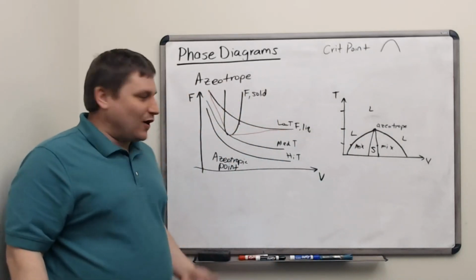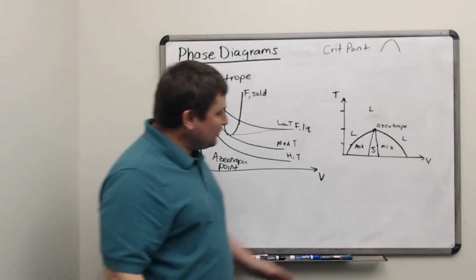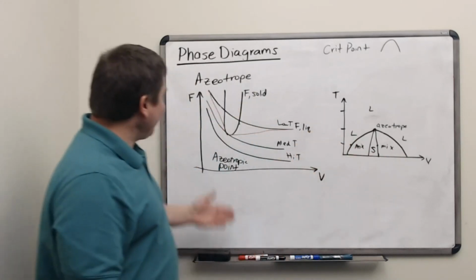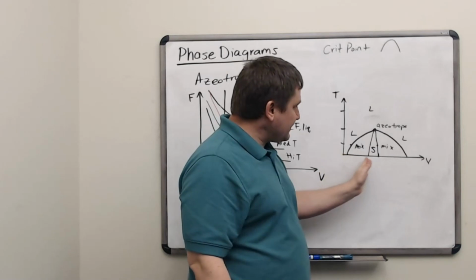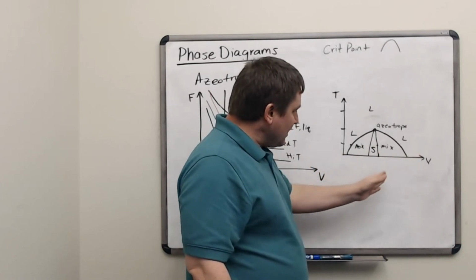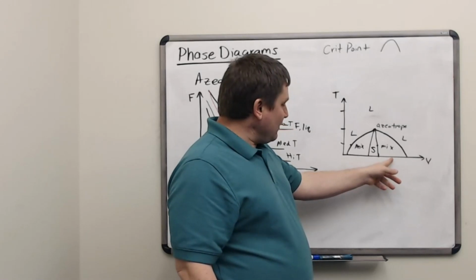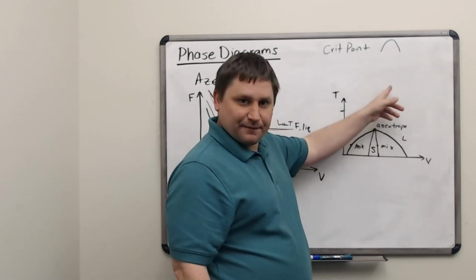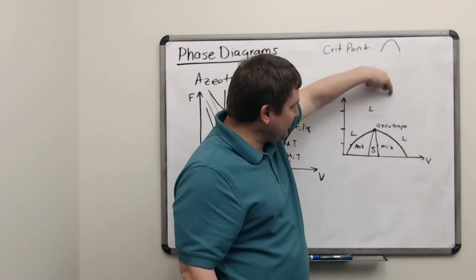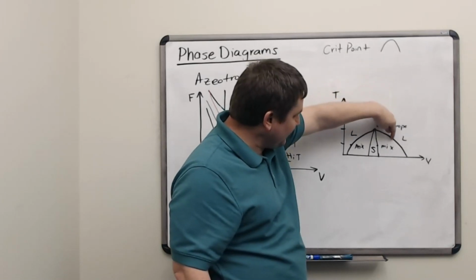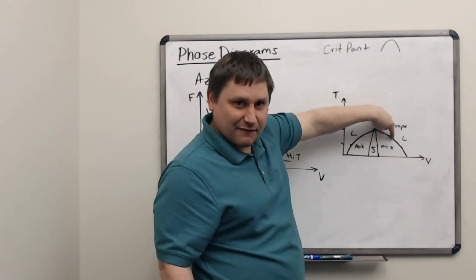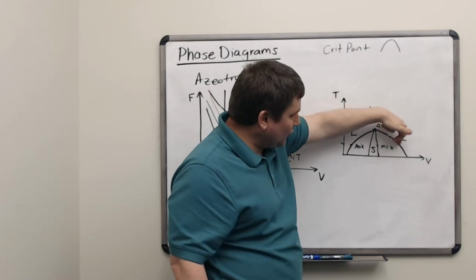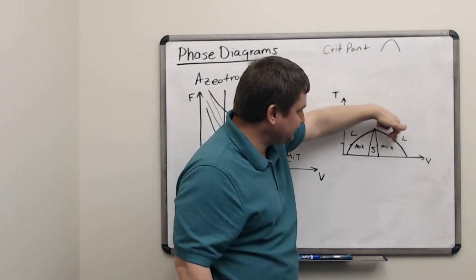Now, what does this mean? Why is this interesting? Well, if you look at what's happening here, on this graph it's versus volume because I've kind of set this up as a Helmholtz energy. But if you set up your system at different volumes, right? Say you're at a volume here, then what you're going to encounter is a mixture of liquid, and then all liquid. So if you started at this point all liquid and you tried to cool, you would go down to a certain temperature here, and then you would start forming some solid, right? You have a mixture of liquid and solid. That's what's in this region. The mixture would be dependent on a lever rule between these two mixture sides.